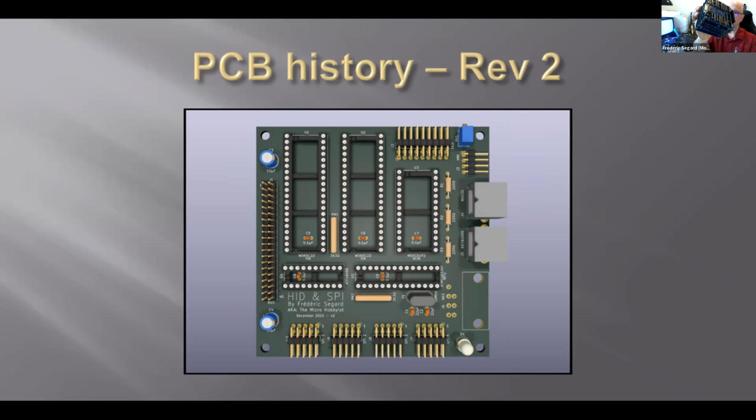And there was an issue with the clock also. I did not buffer the clock properly, so each time I probed it, everything was okay. But once I unprobed it, the computer was going haywire. So there was an issue with capacitance somewhere, and the probe fixed it when I probed it with my scope. Kind of weird.